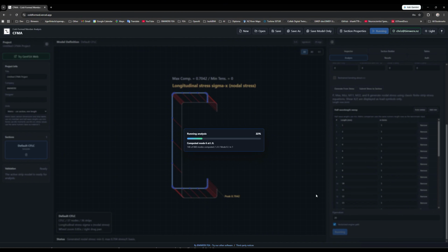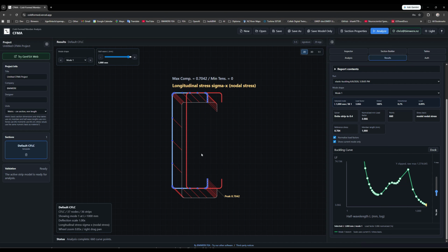And you saw there at the bottom it said 20 eigenvalues. So you can set the number of eigenvalues or modes that you want to compute. At the moment it's 20. So it runs through all of those stations, and you can see it's a total of 660 computations, but it does it reasonably quick directly in the browser. Once it's finished, it'll default to the results view here.